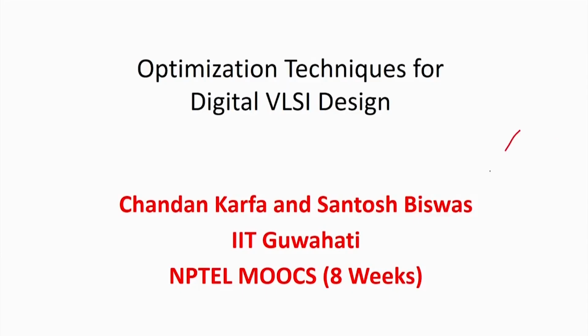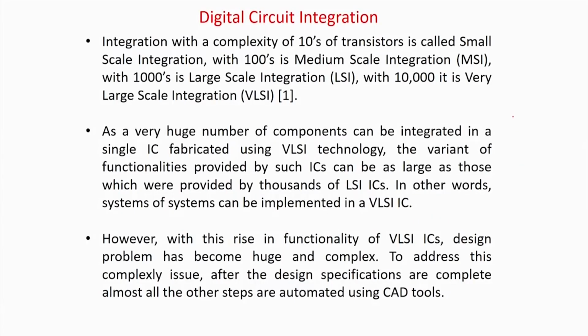There are three basic things you have to optimize. First, I should be able to process the input at an extremely fast rate, so I want a megahertz, gigahertz, or even extremely high frequency, so that you can process the data in just a click. Second, we want very low area overhead. Why? Because the more area overhead you have, the larger your circuit will be and the more cost. So you want a circuit with very little area overhead to do the same purpose, and at the same time, nowadays we are also talking about power. So you have a three-part optimization problem: area, power and speed.